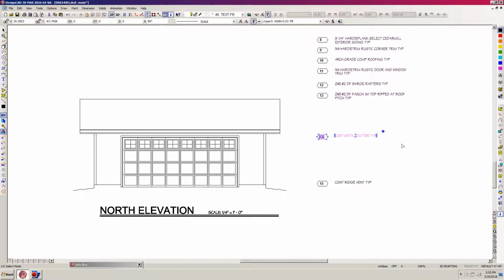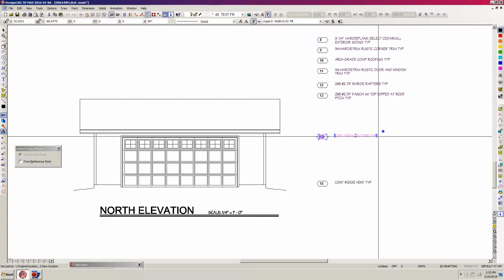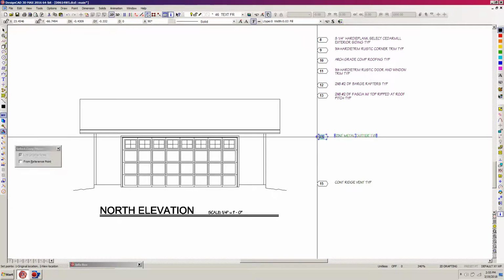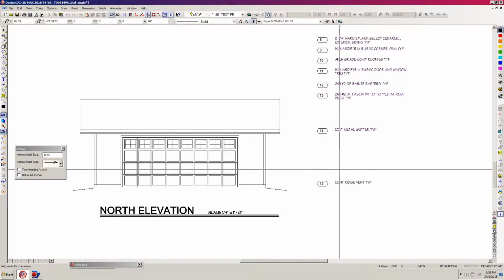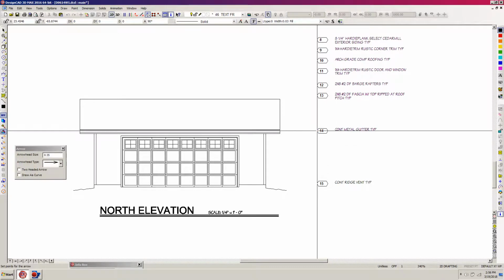And actually, I'm going to move that up a little further, because what I should have done was to set the handle on the point of the sheet note box. So gravity move, hit M, and take this up until it's on the gutter here, about like so. And there we go. So now I'm going to draw an arrow to it using the arrow command, the greater than command. And I'm still in layer 46, which I want to be in. And I'm hitting H for orthogonal mode because this is going to be a straight arrow.